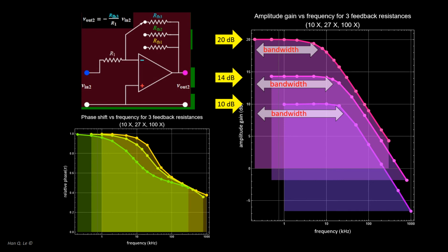A common convention defines the range where the signal amplitude drops to about 1/2 of its maximum as 3 dB bandwidth. What is the meaning and implication of this? An example will be discussed in Part C, in which the optical signal of a household infrared remote control is analyzed.